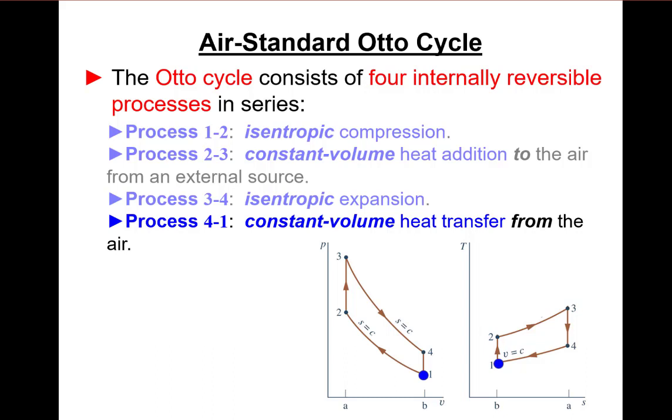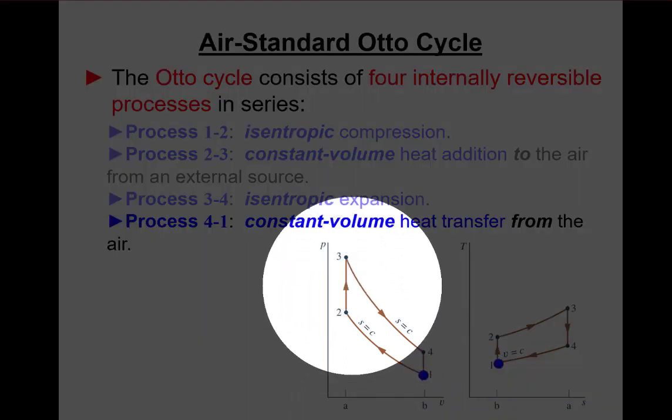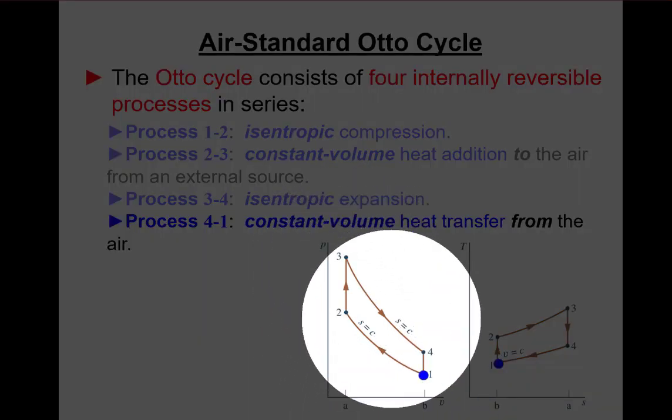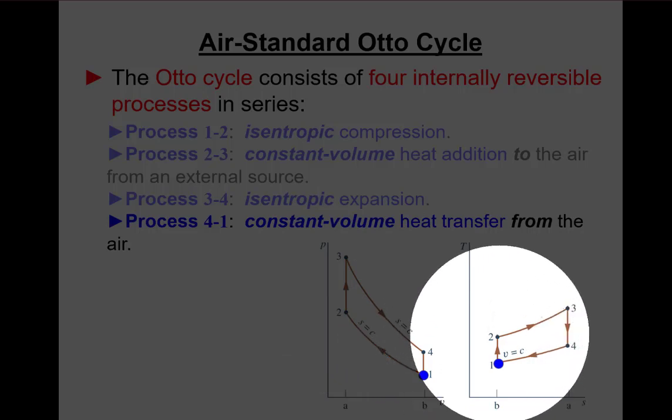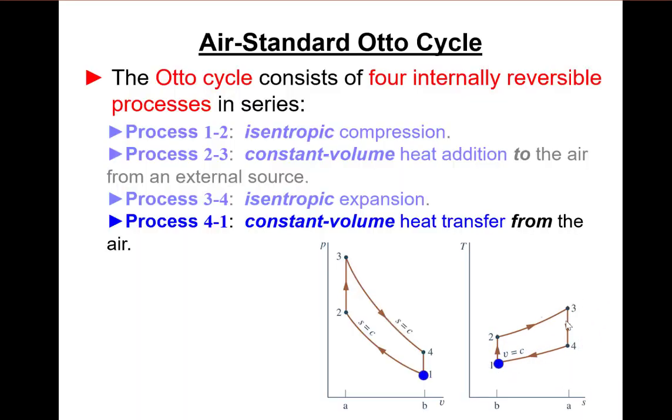It's pretty useful to understand how to draw all of these cycle analysis diagrams for the different cycles we'll talk about. Here, again, the vertical lines on a PV diagram mean no work. That's where the heat transfer happens. And the isentropic processes are the vertical lines on the TS diagram. So we can use the VR ratios, and we can use expressions with k in the exponent.